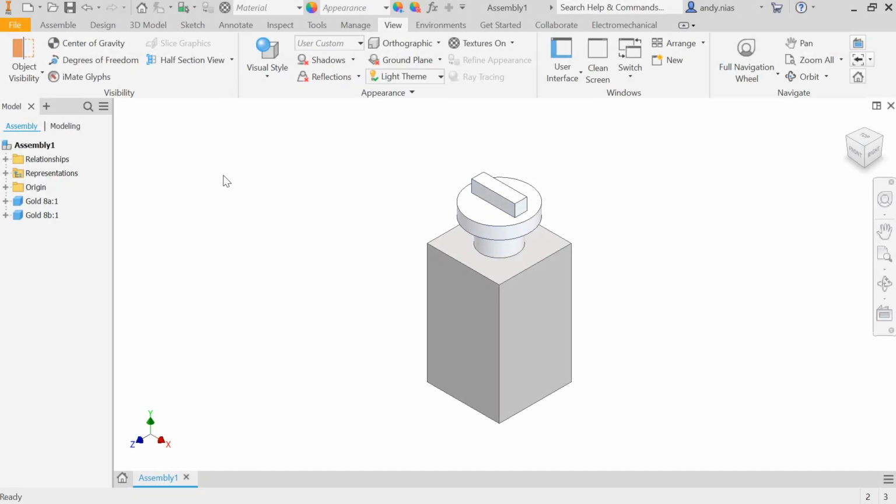So I'm going to make a few changes to this assembly I put together earlier, using the center axis constraint to insert this peg into a hole. I locked it up so that this here is parallel with this side, but I now want to change it so it's put at an angle. Now in order to do that, first thing I need to do is to find the constraint that's stopping it rotating, and remove it so I can put the one I want in.